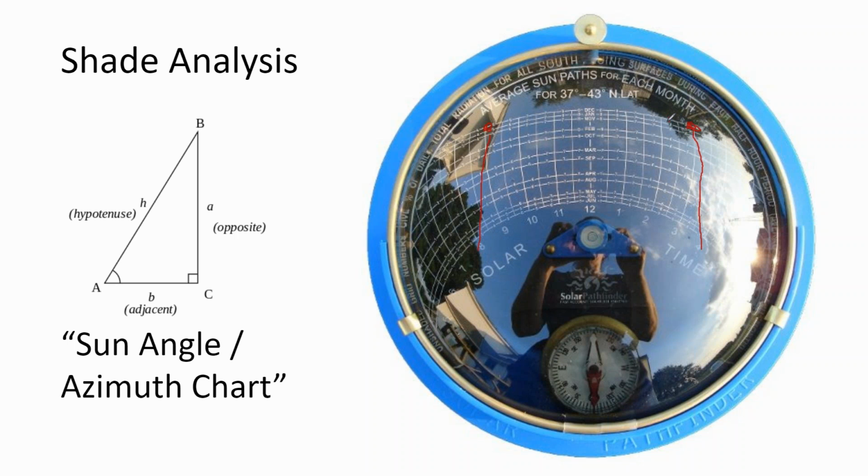So this is a fairly unshaded spot, but once the sun gets into those branches there, it'll turn off the array. Even though the tree will lose its leaves, the branches can still diffuse the sunlight.